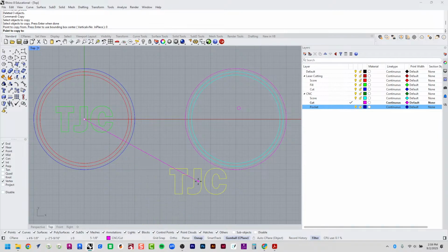And then what you want to do is, because I have the center OSnap enabled, I can come in here now and I can find the center of any one of these 3 circles. The center of each circle is the same exact point. So I can find the center of this circle, that circle, or the other circle. Really doesn't matter. So now that I can see it's identified the center of this piece of geometry that I'm hovering over, I can go and click that.